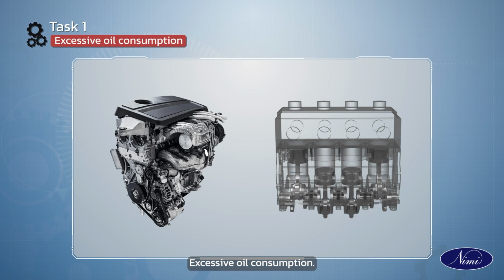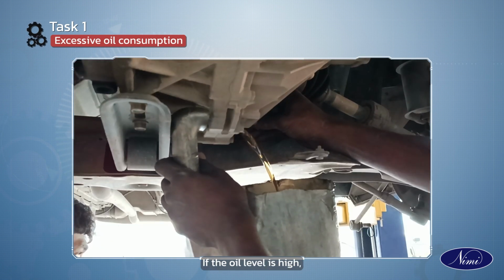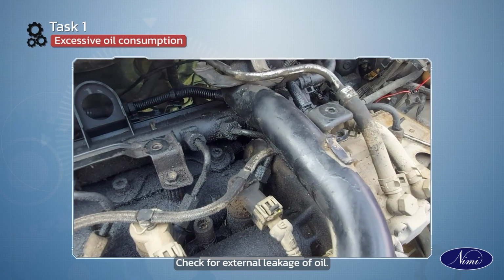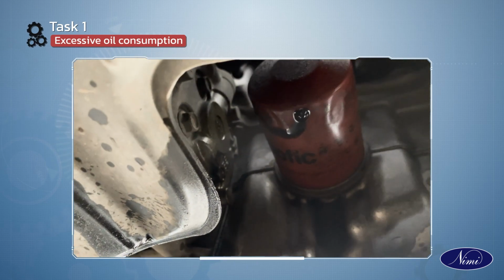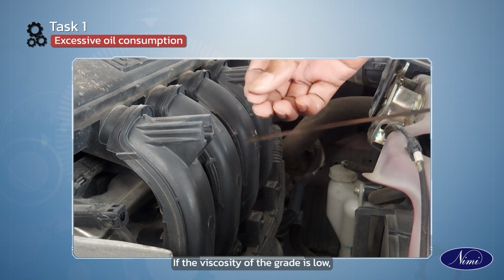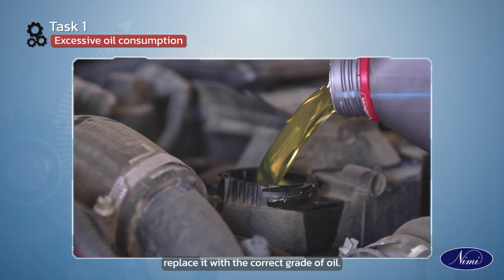Excessive oil consumption. Check the oil level. If the oil level is high, remove the excess oil. Check for external leakage of oil. If any leakage of oil is found, rectify it. Check the grade of the oil. If the viscosity of the grade is low, replace it with the correct grade of oil.